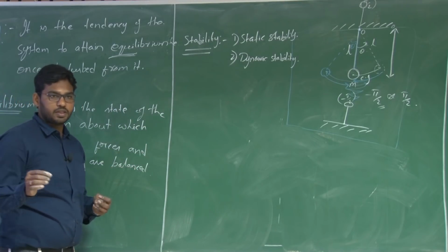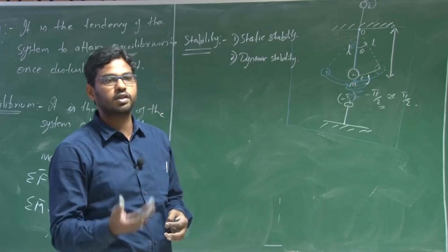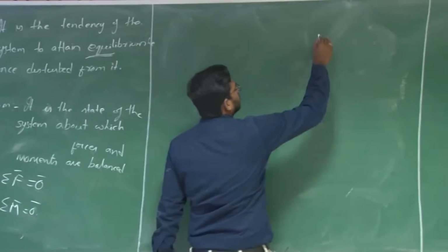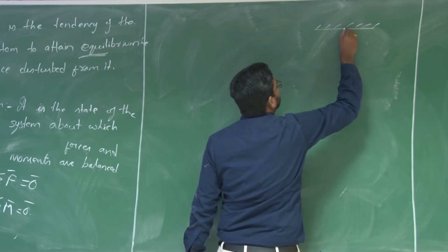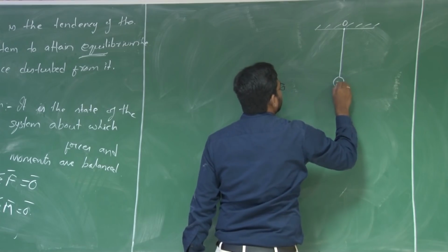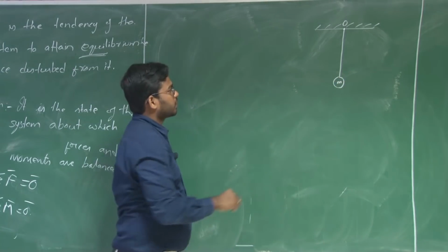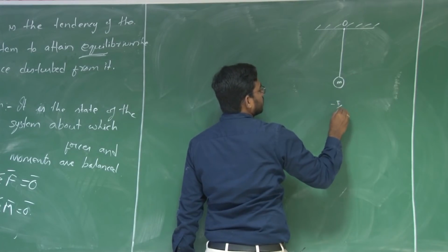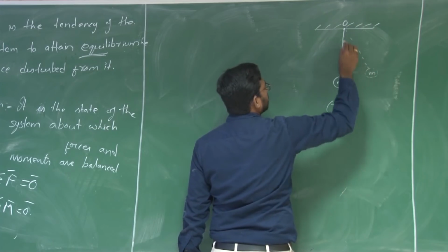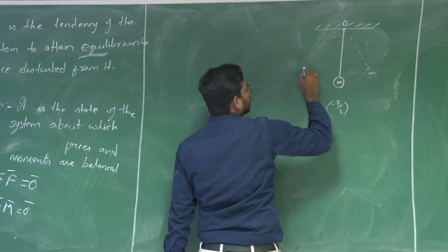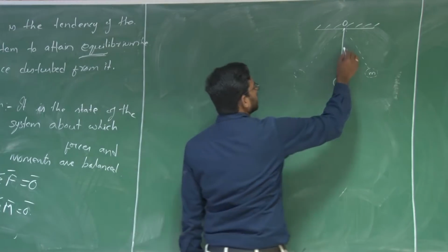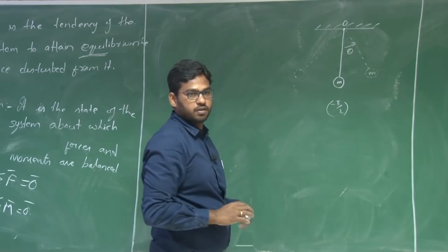Even while varying the CG, what we witnessed is that the stability of the system is changing. So let us see how the stability changes as the CG varies. Again in this pendulum case, at this particular equilibrium location, which is minus pi by 2, we say this is a stable equilibrium. If there is enough friction, it helps this pendulum come back towards its initial equilibrium. So in this particular case we considered it as a stable equilibrium. Why?